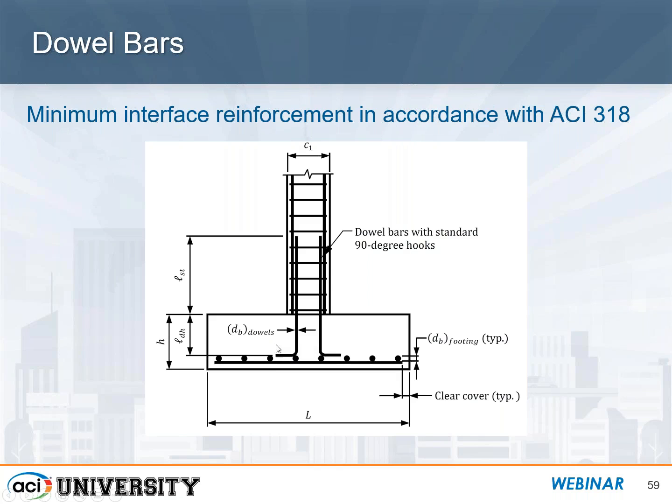You have to take that line above where the bend is and not consider anything below it as contributing to your development length. It's a code requirement. A hook in compression is not recognized as being part of the development length of that bar in compression. You have to go above that, the bend diameter above where that hook is. And that distance would be shorter than that shown here.